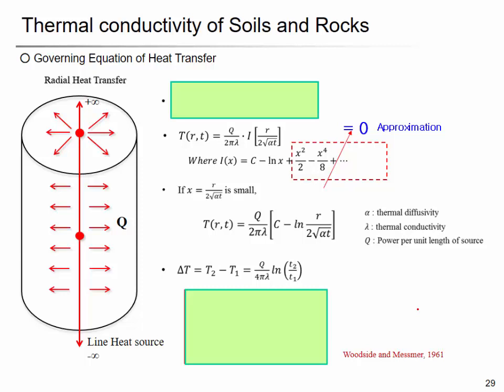So, how can we measure the thermal conductivity of soils and rock? Or any solid, or liquid, water, gas. So thermal conductivity is one of the physical properties, like density, right? Or like maybe strength, or permeability. It's one of the physical properties very important in geotechnical engineering and geology. So these days, people use shallow geothermal energy or deep geothermal energy. There are also many infrastructures related to energy and heat, so the investigation of the thermal conductivity is important here for geotechnical engineers.